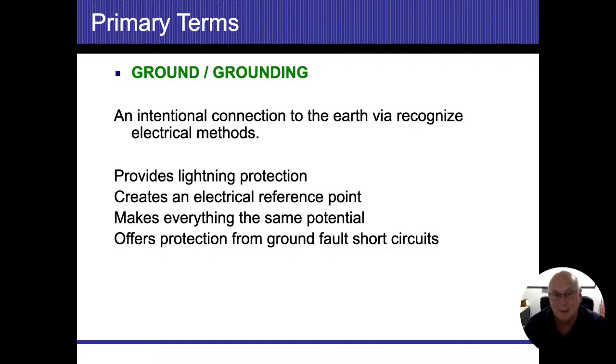Whatever electricity is available on the system will attempt to flow. Far more than that 5 amps that the earth is going to allow. Far more than the 15 amps that the breaker is going to trip off at. Even if that 15 amp breaker is broken, it's going to be far more than the 100 amp or 200 amp main disconnect breaker. I really don't know what the number is, but it's far greater than that 200 amps.